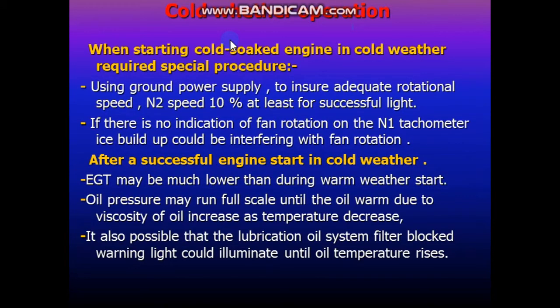Cold weather operation. Starting a cold soaked engine in cold weather requires special procedures. Use a ground power supply to ensure adequate rotational speed, at least 10% N1, for successful light-off. If there is no indication of fan rotation on the N1 tachometer, ice build-up could be interfering with fan rotation. That means when you start the engine in cold weather, you have to use a ground power supply.